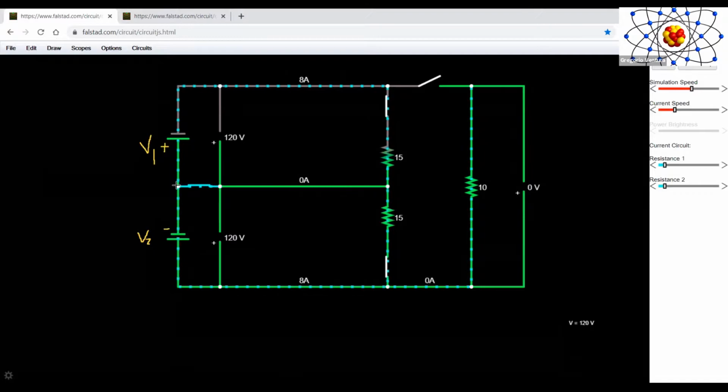I want you to notice that in residential also, this other conductor here is also called the grounded conductor, because right at the panel, this conductor, which is the white conductor, is connected at the same potential of the grounding conductor. Okay, so let's keep moving.